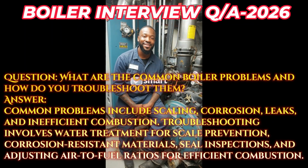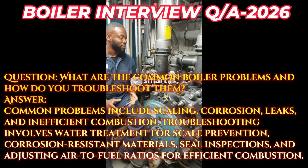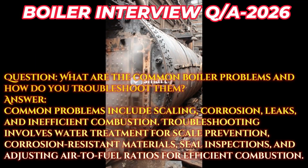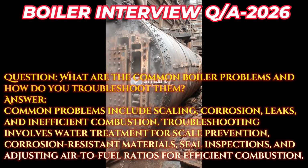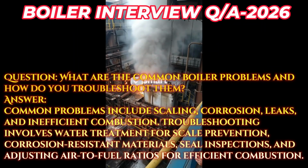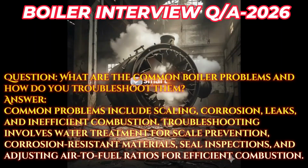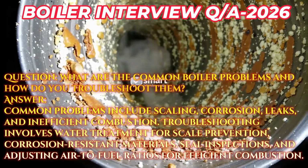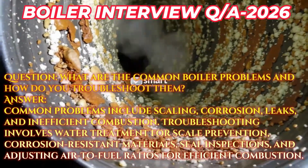Question: what are the common boiler problems and how do you troubleshoot them? Answer: common problems include scaling, corrosion, leaks, and inefficient combustion. Troubleshooting involves water treatment for scale prevention, corrosion-resistant materials, seal inspections, and adjusting air-to-fuel ratios for efficient combustion.